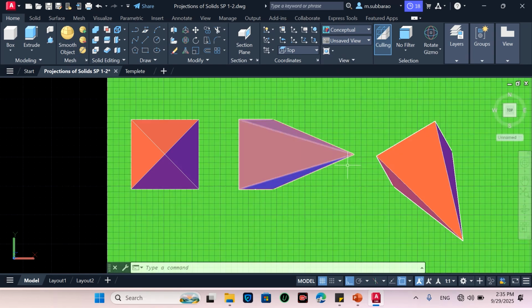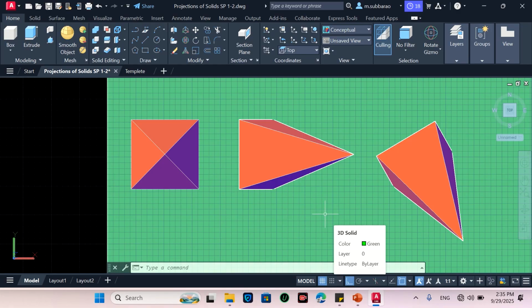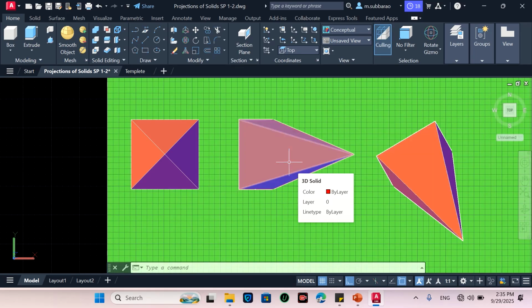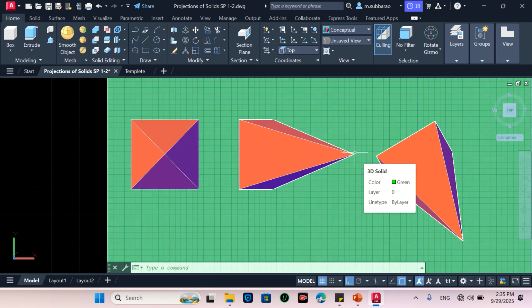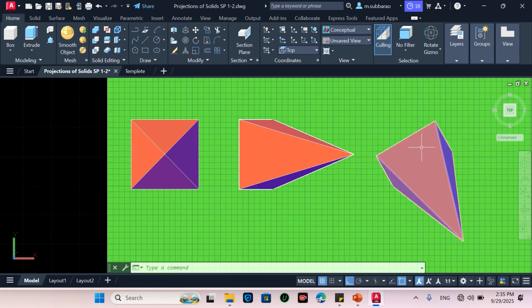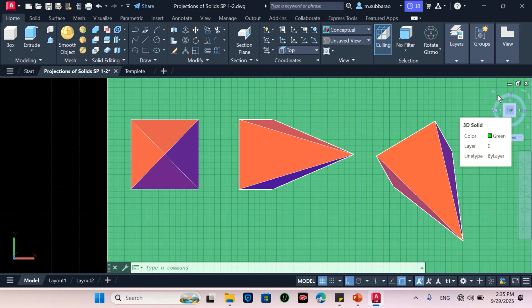Now when you are rotating the solid, making the axis 60 degrees with the vertical plane, at that time you observe this shape, and this shape is the same with the same dimensions. The only thing is the axis is making some other angle of inclination. That is the only difference. So rotating this, the top view will not make any difference in the shape, only the axis angle will change. So now this is the top view.